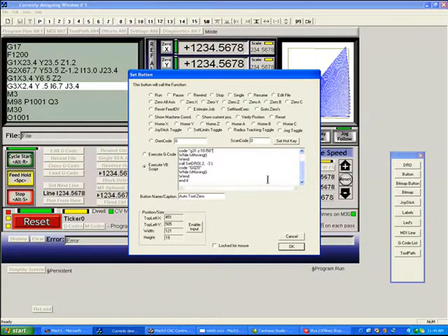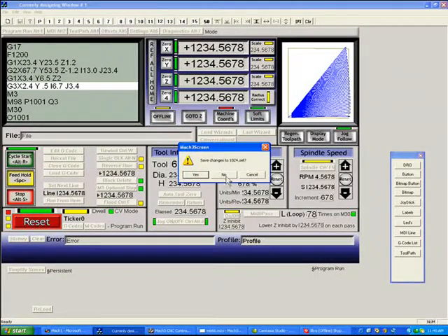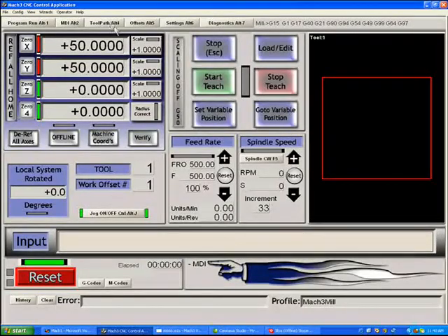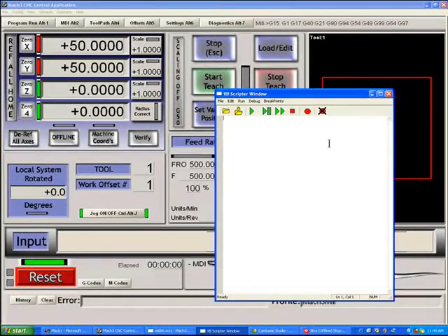And you'll get pretty handy at that if you practice with the Visual Basic Scripter and begin to understand what the commands do. Again, I encourage you to open up the scripter, load a few macros, hit play and see what happens. Make sure that your control is reset and ready to move when you're hitting play on a script if you wish to see the end effect of it. You don't have to save it as a file. You can simply open up the Visual Basic Scripter, type a command like Code "G0 X10", and by hitting play, your X will move to 10.